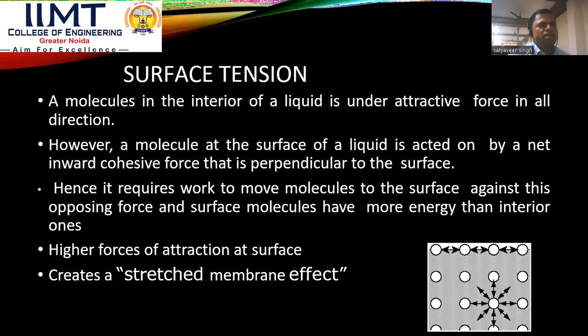Now we will understand the basic concept of surface tension. In case of surface tension, we have a figure in which we have different molecules, say a molecule in the interior of the liquid. A molecule in the interior of the liquid is under attractive force in all directions. However, a molecule at the surface of the liquid is acted on by a net inward cohesive force that is perpendicular to the surface.